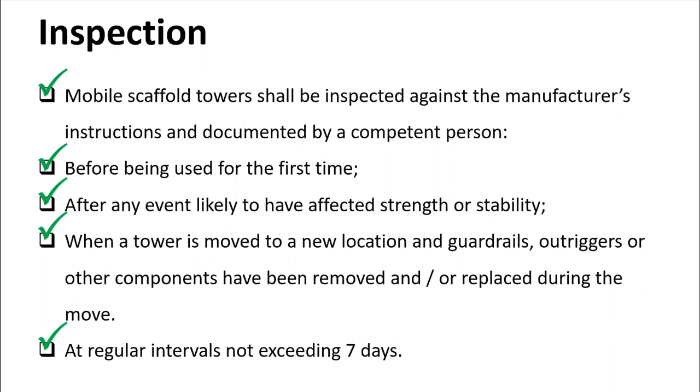So the inspection should be done before being used for the first time, or after any event like bad weather conditions, or when you move the tower to a new location, or at least every 7 days as per the law, you need to conduct an inspection.